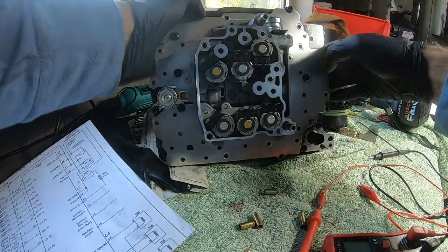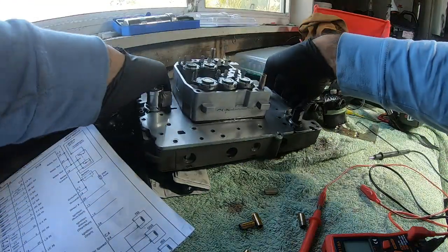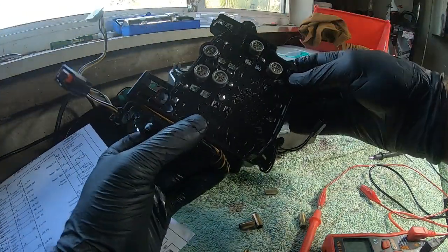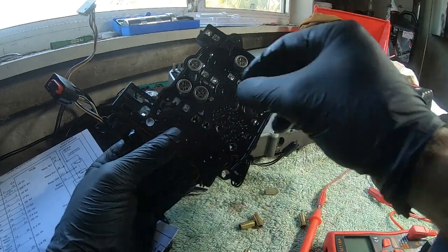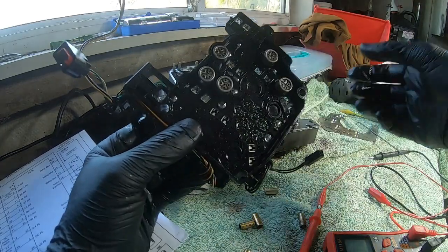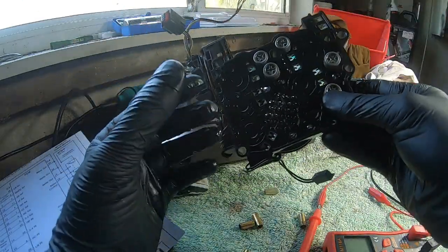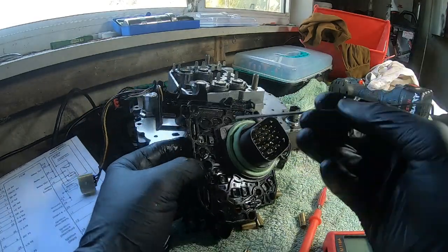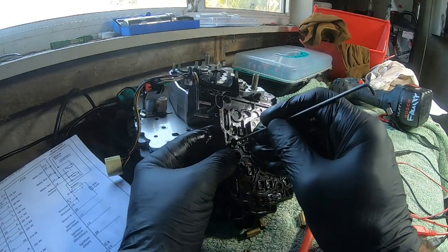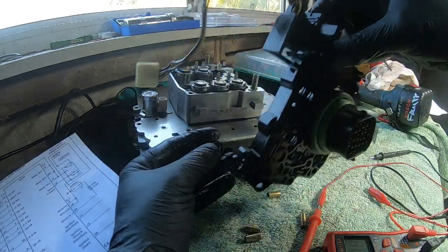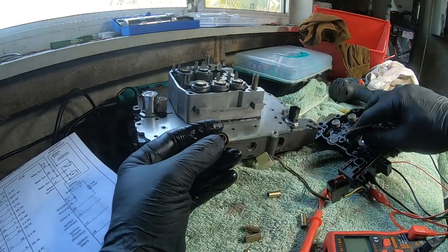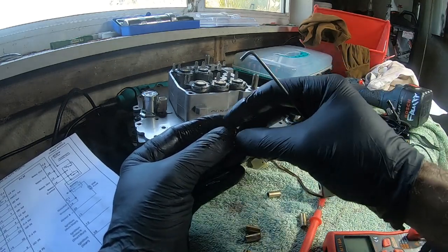Apart from that, let's now go back to the housing that we just removed. Okay. So these are the pressure switches in all their magnificence. The easiest way to take them out is usually from the other end. They are pretty tight, not too tight, but just snugged in. You can see the brass contact from here. So just take any pin and slightly push it out, and you'll have it. There you go. Sometimes they fall off, so be careful, because one of them is already loose, I can see. So yeah, you don't want to lose them.